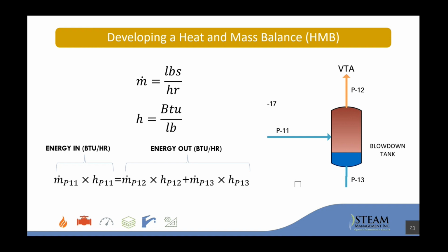Travis Mosher had chimed in on the chat saying the pressure should be set according to how the boiler is designed. Yeah, I agree with that. And then you're going to spec your boiler for what you need, and what the distribution piping is designed for. If your pressure goes up, your diameter of your piping can go down for the same mass flow, and so it's really just a whole design effort.